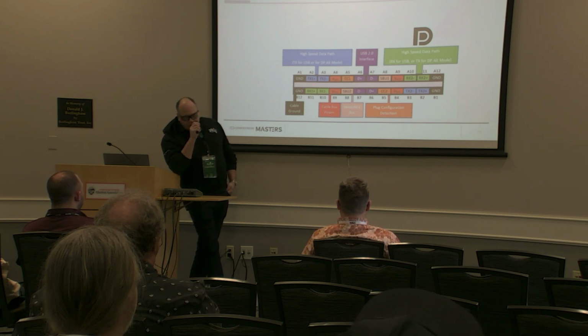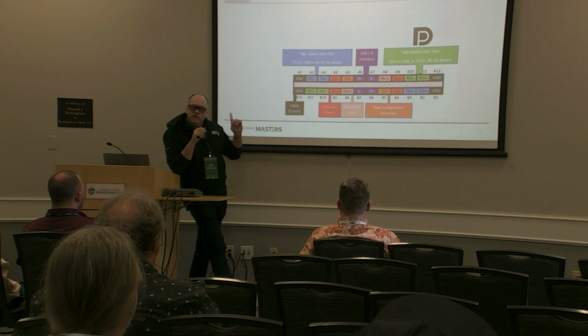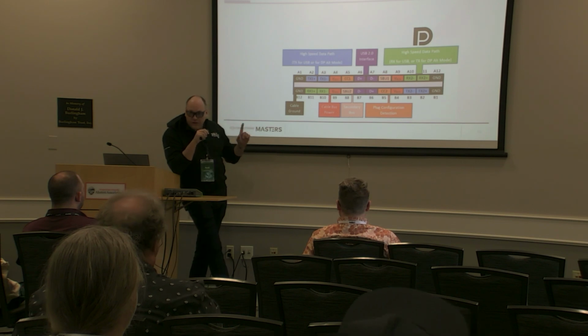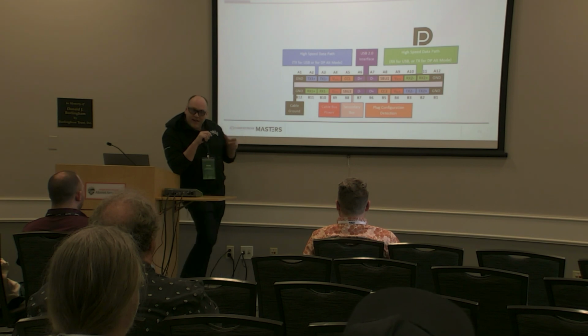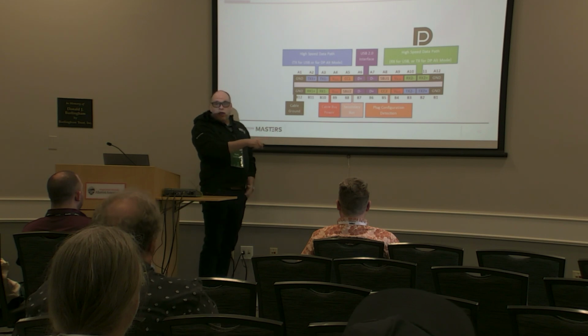Now, there's another thing about this drawing that I want to draw attention to. So we know that in USB 2.0, the first pin was power, right? And we know that in USB 3, that same pin is carrying power. It's got more amperage on it, but it's the same pinout. We're not adding an extra voltage pin. In USB-C, we do add a second lane, right? So here's our VBUS and here's our VBUS. So when we flip it, it's the other way around, right?